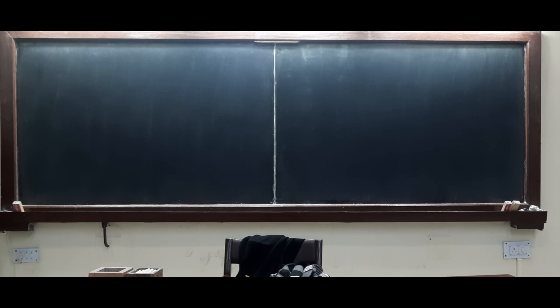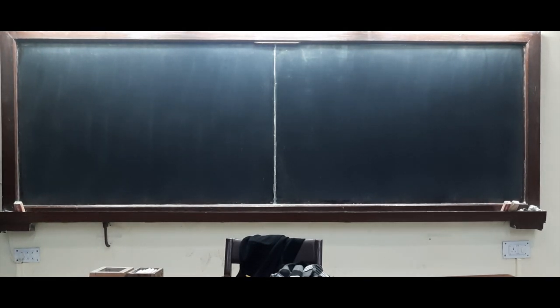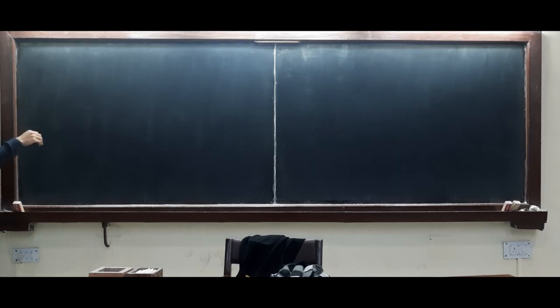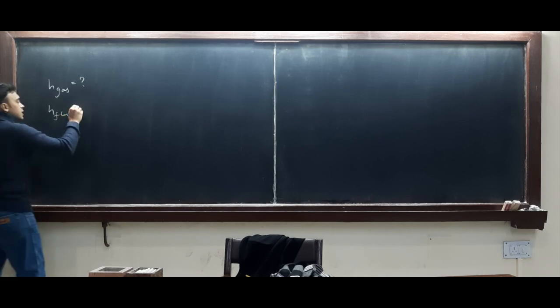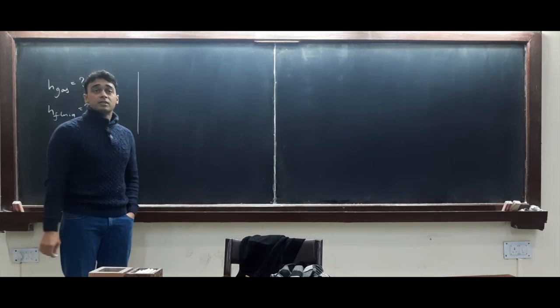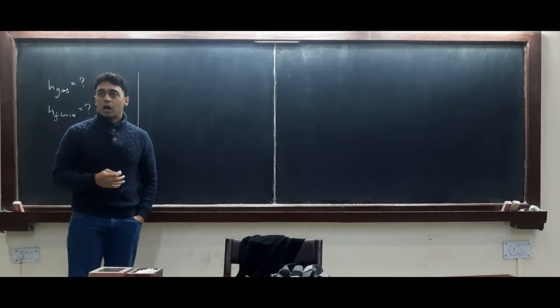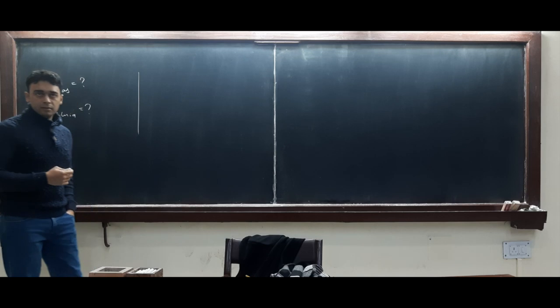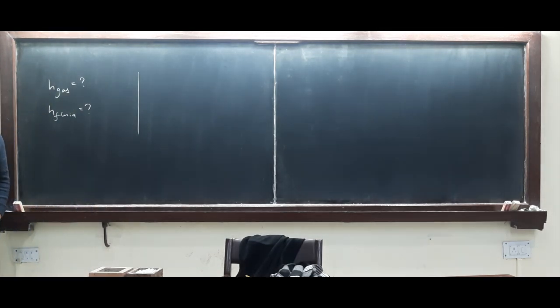Yes? So what kind of fluids are you aware of? Gases and liquids. Generally for gases, could you just check? I've included the values, I think in the third or fourth image, titled appropriately. So what is h for gas and what is h for liquid? But then you also have to tell me, for moving fluids, if you're doing forced convection, how high it can go, right? Because convection depends on velocity.